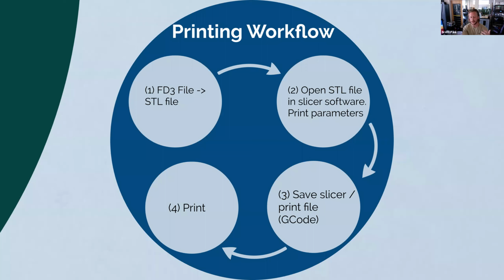So you're going to design something in CAD, and what you'll ultimately end up with is a part or an assembly of parts, and that's going to be an F3D file. You're going to export that file as an STL, which stands for stereolithography, and it's just how the data is stored that makes those two different. There are, I think, 7 different universal CAD files that can be downloaded and interpreted by pretty much all CAD software, and an STL is one of the most popular of that 7.